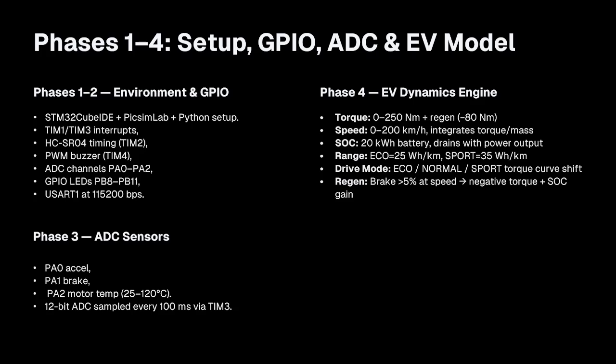In phase 3, we created the ADC sensors, which are developed using potentiometers. The acceleration is connected to PA0. Then the brake is connected to PA1. Then the motor temperature is connected to PA2.